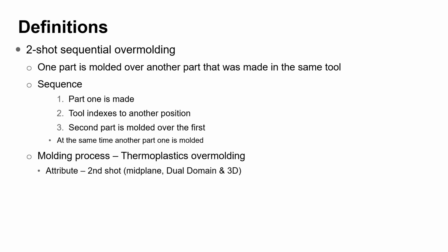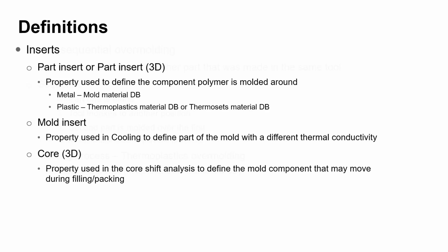Actually, the molding process is thermoplastic overmolding at this point of time, and the second shot could be midplane, dual domain, and 3D, but today we would be referring only to the 3D part of it. So the insert could be a metal or it could be a plastic.